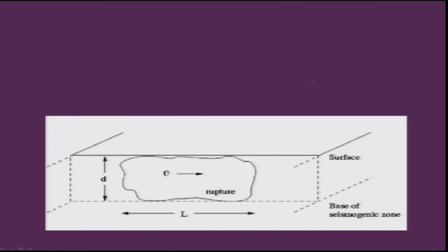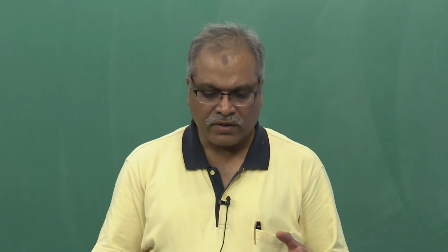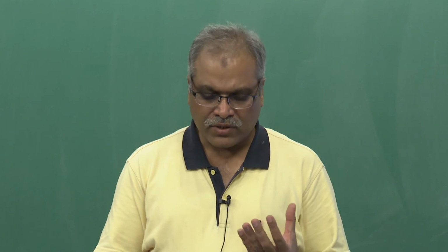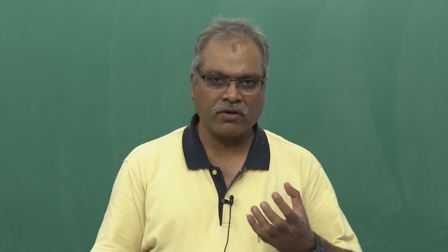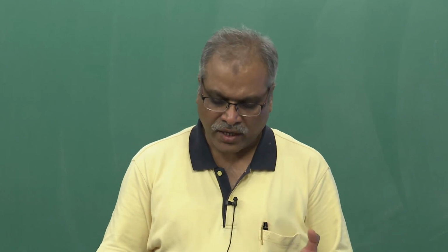So for the new scale which was developed, it was thought, why not take the overall deformation pattern, or the energy which has been released along the fault plane completely. And if you remember, we were talking about how along with the main shock there will be small magnitude or micro earthquakes which occur after the event, which are termed aftershocks, and those aftershocks are also taken into consideration to calculate the magnitude or the rupture area.